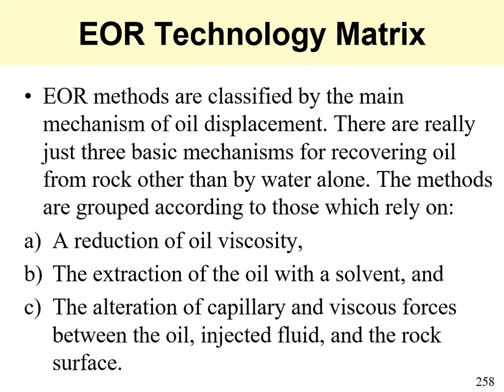So EOR methods are classified by the main mechanism of oil displacement. There are really just three basic mechanisms for recovering oil from rock other than by water alone. The methods are grouped according to those which, firstly, rely on a reduction of oil viscosity. Secondly, the extraction of oil with a solvent. And thirdly, alteration of capillary and viscous forces between oil, injected fluid and the rock surface. So these are the three basic mechanisms which EOR methods exploit.